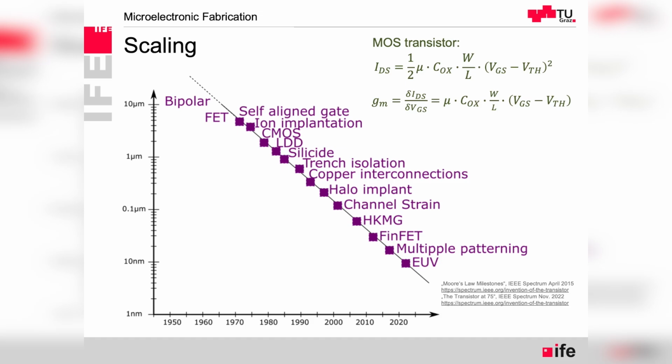So directly on the scaling, we can also analyze the interesting topic of how the transistor oxide parameter and transconductance would be changing. So generally, transconductance we would like to keep constant. Threshold voltage we would like to scale down because the power supply decreases. And so mainly the oxide we would like to adjust correspondingly.